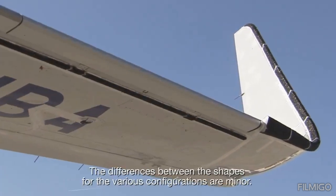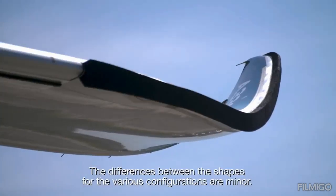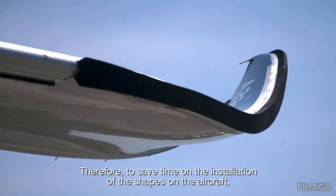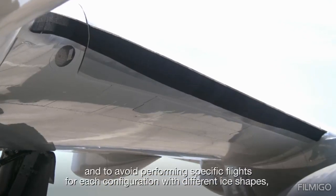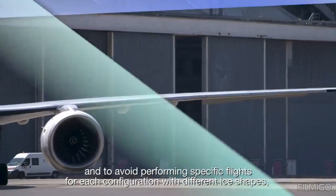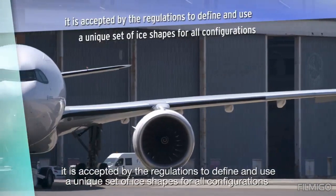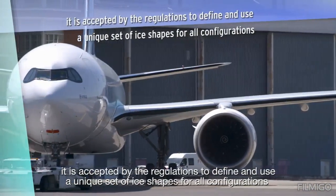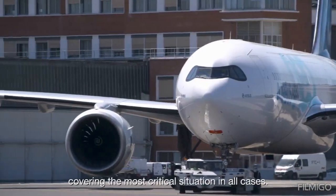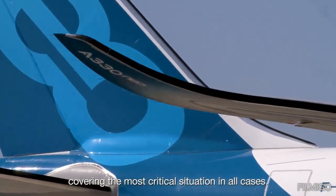The differences between the shapes for the various configurations are minor. Therefore, to save time on the installation of the shapes on the aircraft and to avoid performing specific flights for each configuration with different ice shapes, it is accepted by the regulations to define and use a unique set of ice shapes for all configurations, covering the most critical situation in all cases.